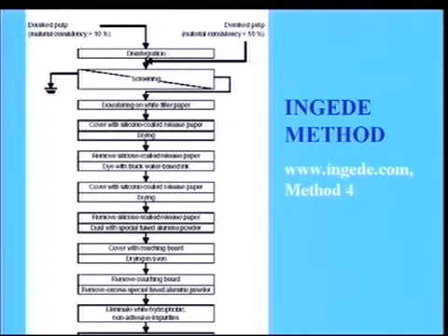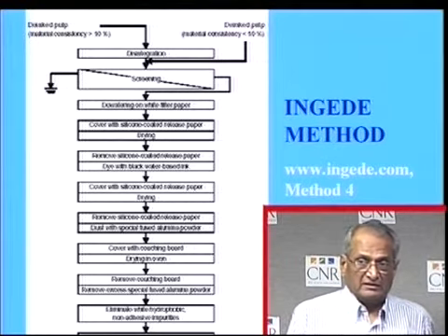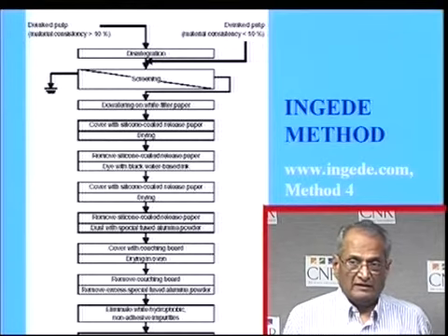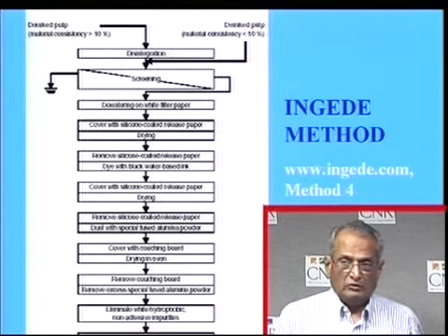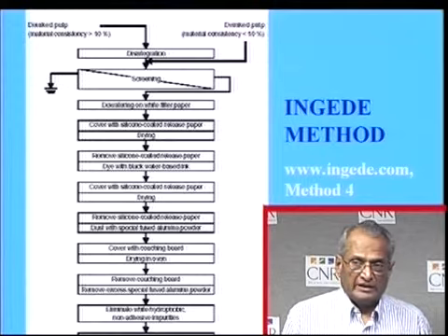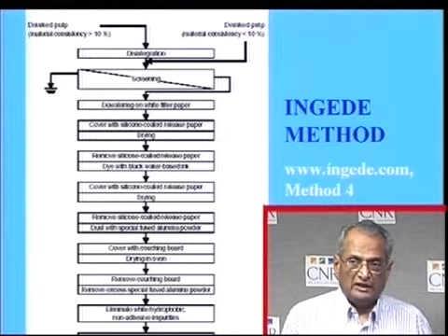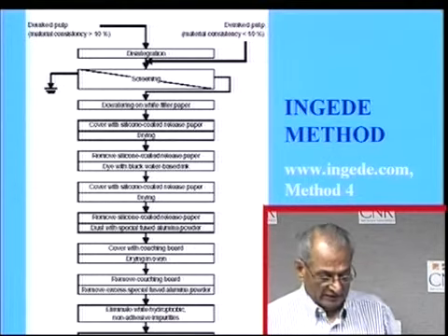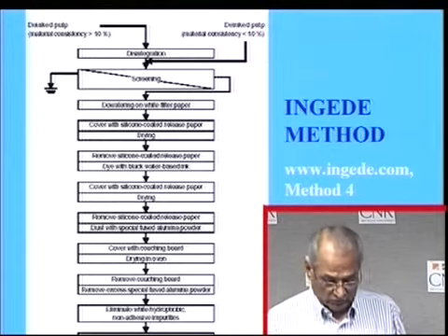And the purpose of the black dye and the alumina powder is to distinguish between the non-sticky ink particles and the black sticky particles, because both the ink particles and stickies are black. And so when you sprinkle with the alumina powder, only stickies will adhere to the alumina powder, but not the ink particles, which are non-sticky. And that is why you go through this detailed procedure.